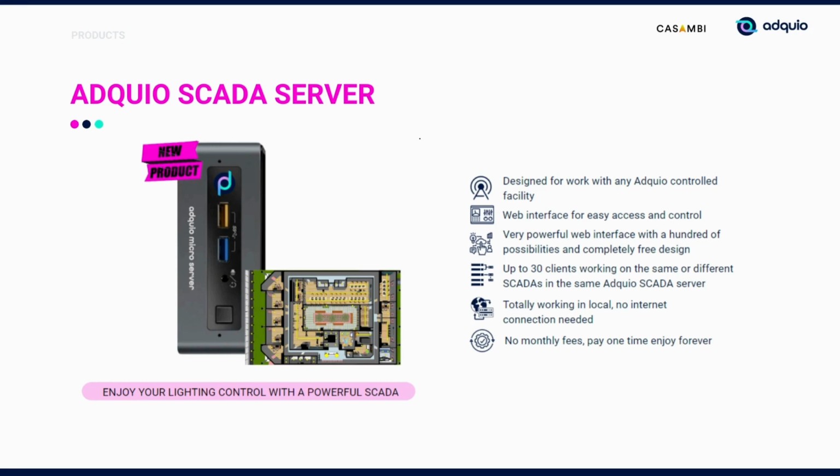You can change their position. You can use the pre-designed objects that the SCADA itself already incorporates, such as buttons and sliders, and connect them to the variables of your controller. And from the screen, you can then modify values in real time of your installation. In this way, we have two types of controls: one to visualize the status of your installation, and another to interact with it through controls within the SCADA itself.